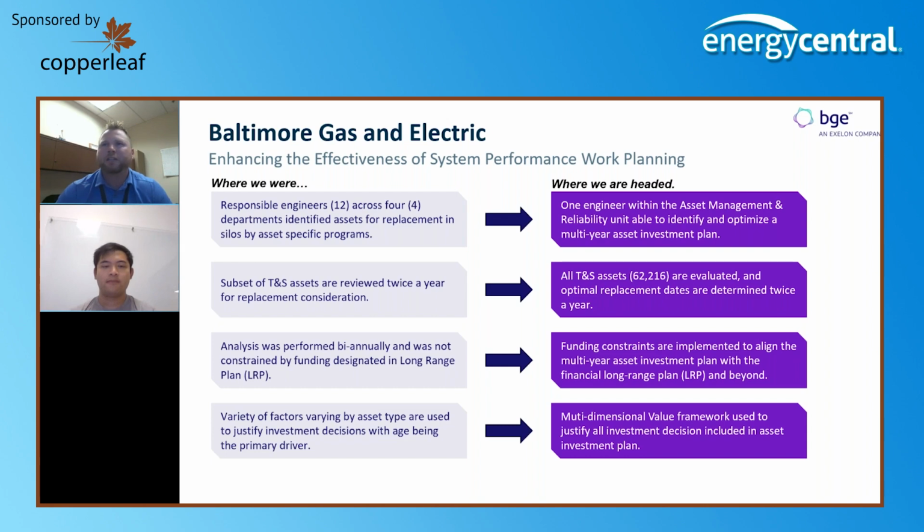And I think one of the big changes that we've been able to make, that we didn't have a mechanism for previously, was this whole idea of really understanding consequence of failure. So you have the probability that a piece of equipment's going to fail, and that's related to its age and other environmental factors that it's experienced. But every circuit breaker that you see on that first list, in that population of 600, doesn't have the same consequence if it was to fail.